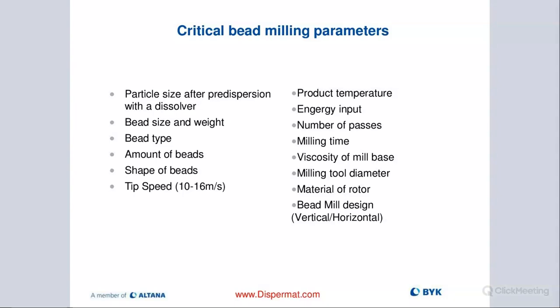If you go lower than that, then you're going to eventually heat up the material and the chiller will no longer be effective enough to continue cooling the material, and then you'll have to shut down, and it's a pain. So don't save, always get at least a comparable chiller to the motor power of the dissolver.